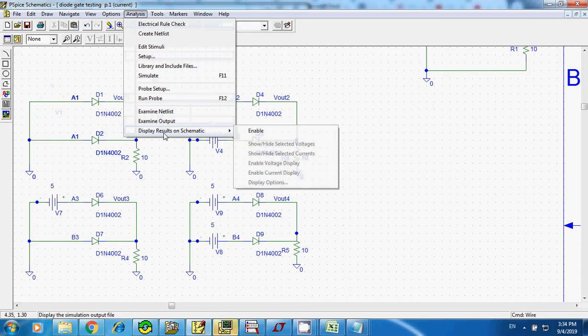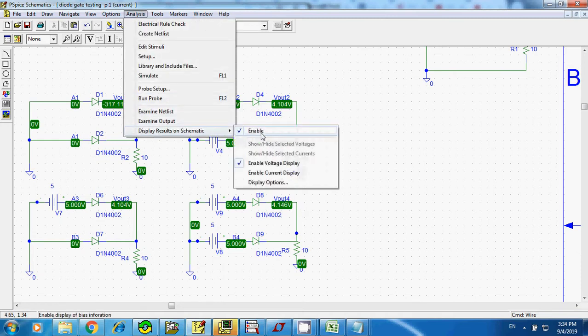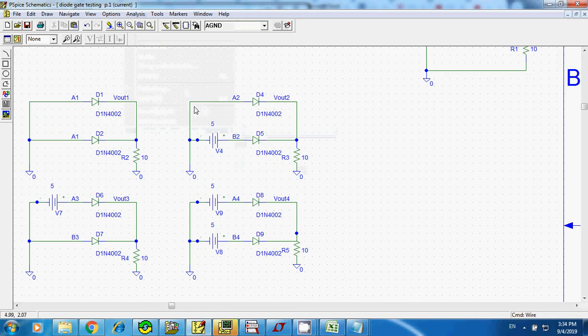Let's take a look at your output. Enable. Okay, in this case you have our input 0, 0. That means give you V out just right here. It's very low. That's 0. And for your input 0, 1, we have output to be 4 or digital logic 1. And this also 1, 0 gives you output to be 1. And for 1, 1, of course, you get the output to be 1. Okay, so this explains how the circuit works, and uses the diode as the digital logic gate.